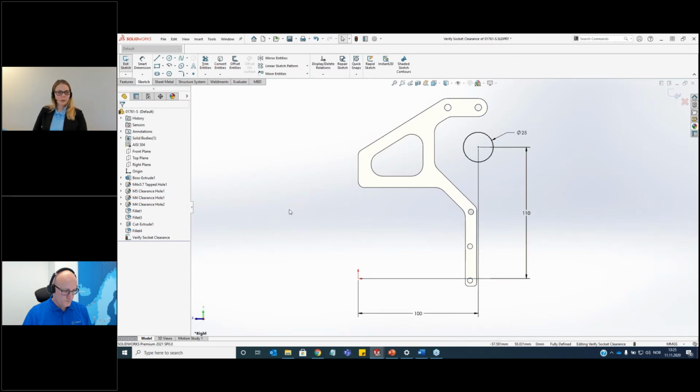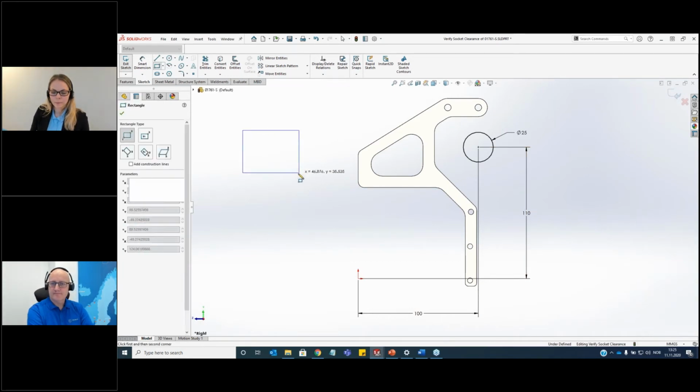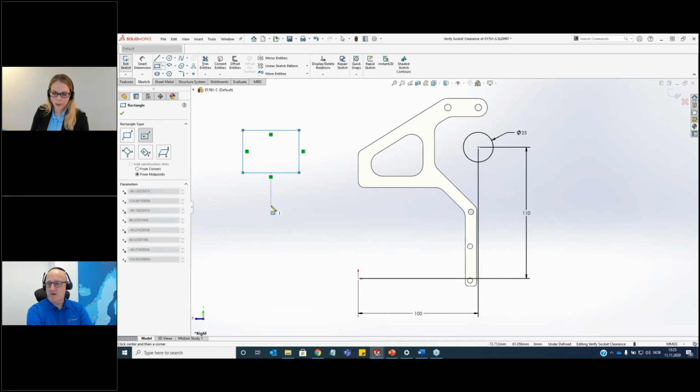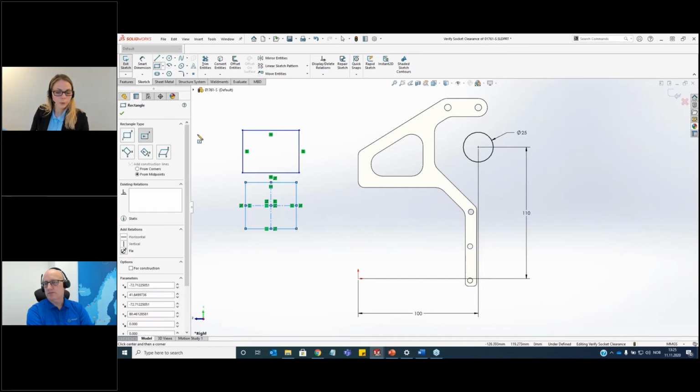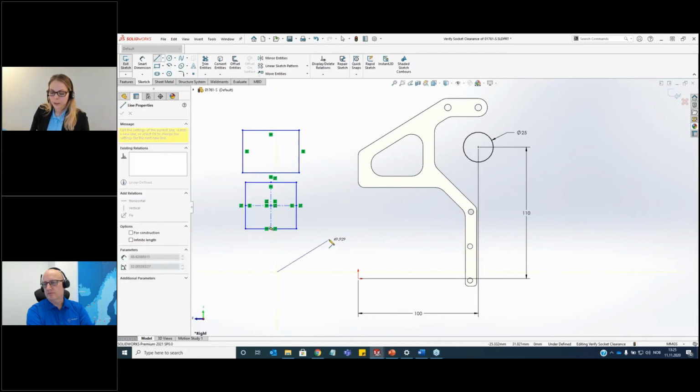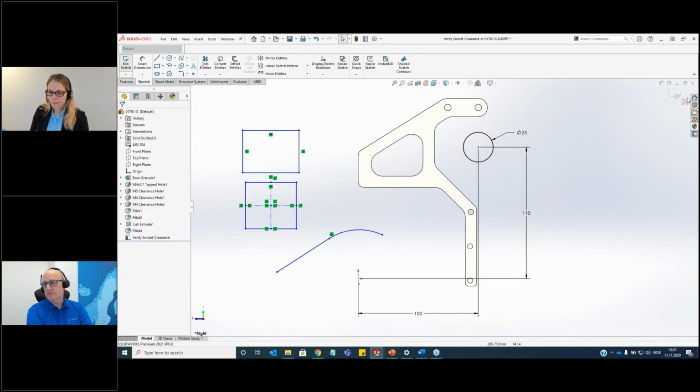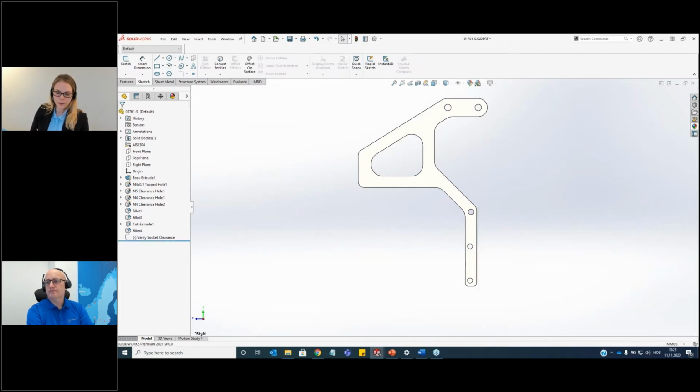So Lars already mentioned the S key, or the SOLIDWORKS super secret special key, as we call it. If I use this key to draw a rectangle, I can use the A key on my keyboard to change which type of rectangle I want to draw. If I use the S key to draw a line, I can use the A key to change between a straight line and an arc. And when I'm done with my sketch, I can click the D key to get the confirmation corner at my pointer and then easily exit it.